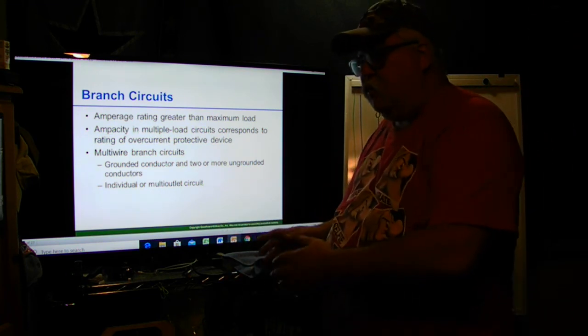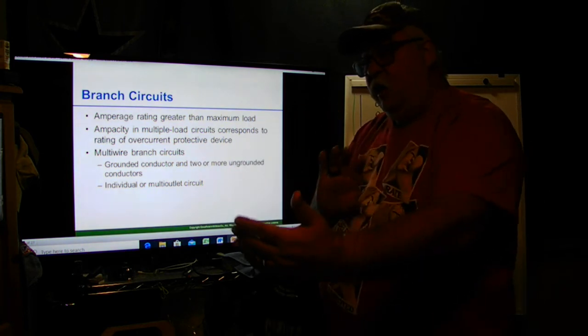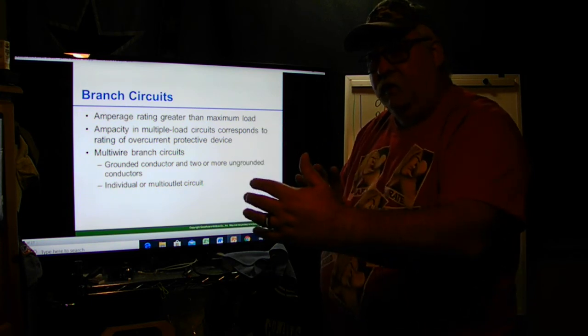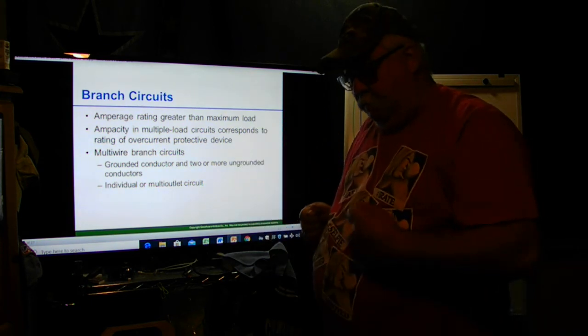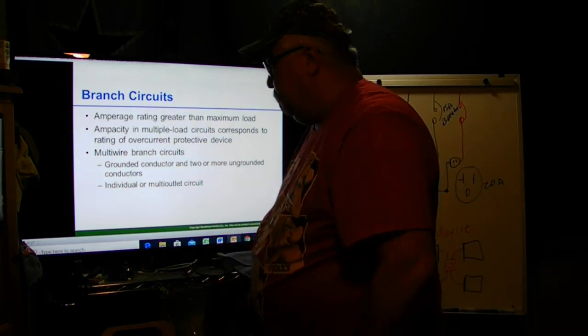Okay, 12 gauge wire. I'm fine because I can carry it. I'm not exceeding that 16 in case it stays on for an extended period. So I'm allowing myself. So that's what you have to look at. You're sizing the circuit according to what's being plugged in.